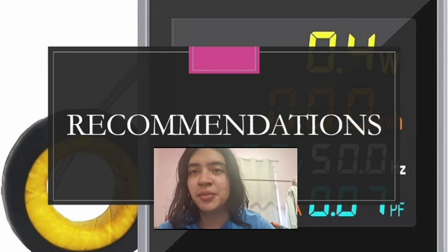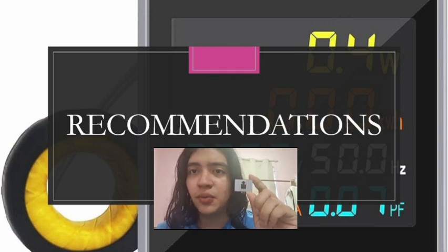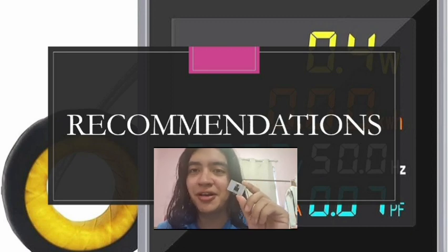And the last thing, but no less important, is be careful with your musical Tesla coil, because if you touch one component like the MOSFET and this is not well connected or well welded, it's going to heat a lot and it can burn everything. Really, it's very hot if it doesn't connect correctly.